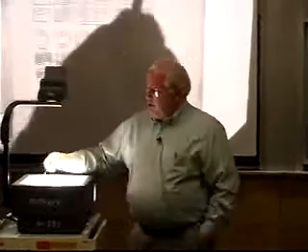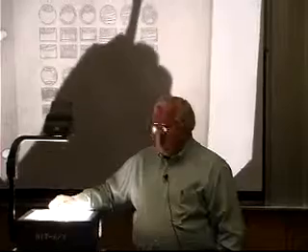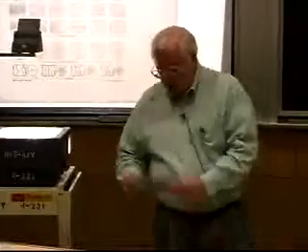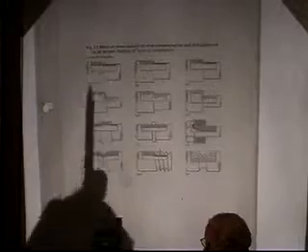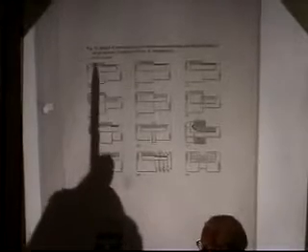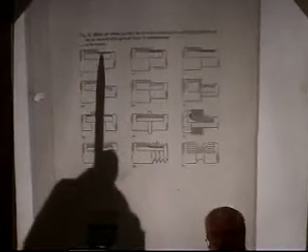But then, in almost all cases, I could see evidence from the shape of the fatigue crack that there was a stress concentration. It might be a keyway, it might be a notch that causes a stress concentration. There's lots of things that cause stress concentrations. This should be in your notes somewhere, but basically, whenever you have a change in section thickness, you'll have a concentration of the stresses. And you can actually draw lines.